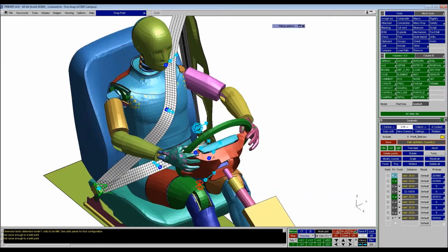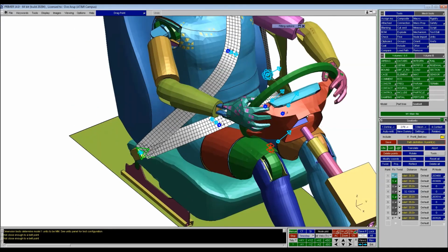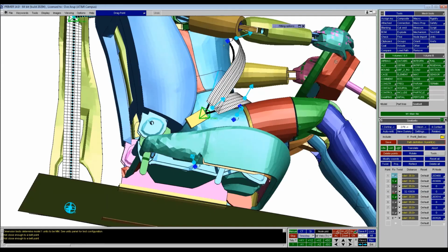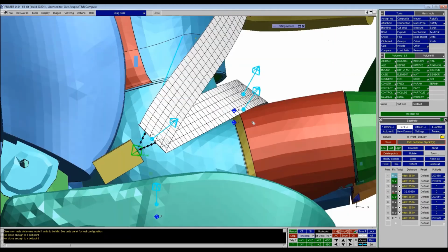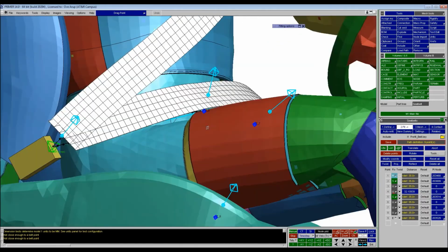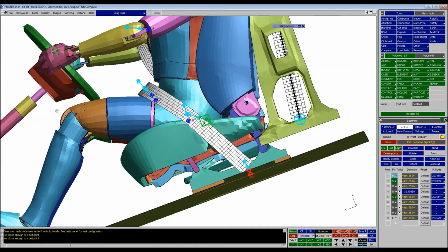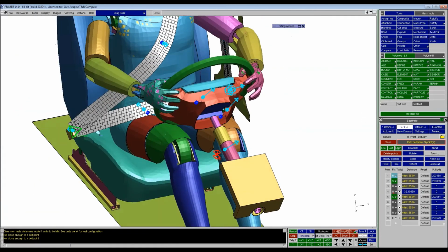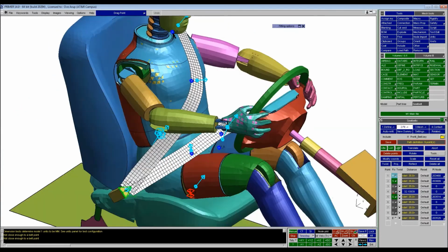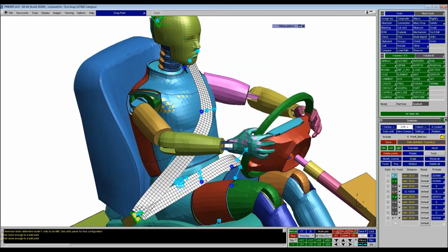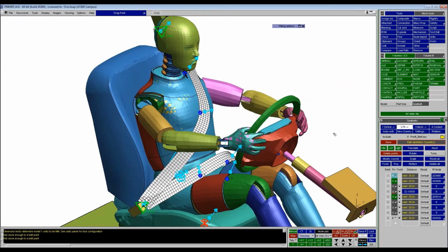So that's how we can modify our belt. And the goal at this point is to make sure that we have no intersections between our belt itself and our structure. Any crossed edges at this stage are going to snag the belt when we try to fit it around our occupant. You can see here when we do this projection, we also get a little small P there, and that's just to note when we're in other menus that we've changed the projection of that point.